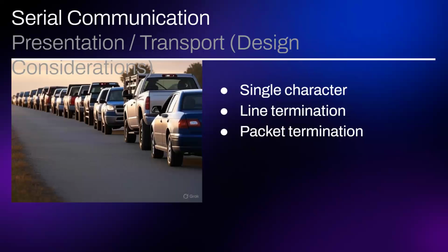Same thing with the packet. You can do either a terminating character, or you can do a length somewhere in the header, at the beginning of your packet. I've seen a lot of people not do this, and it's a really big pitfall that people fall into. They don't know when to send the packet. The receiving side doesn't know when it can process this. Like, am I done yet? I don't know if I'm done yet.